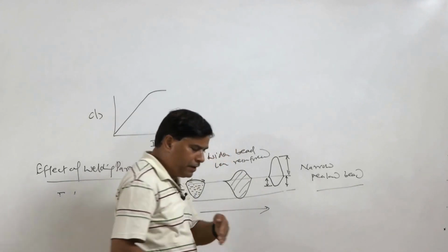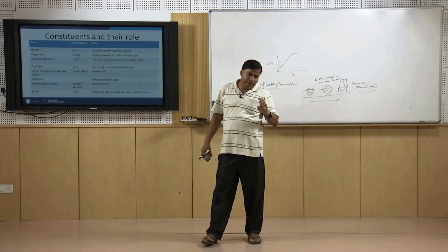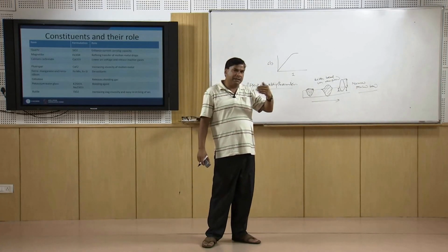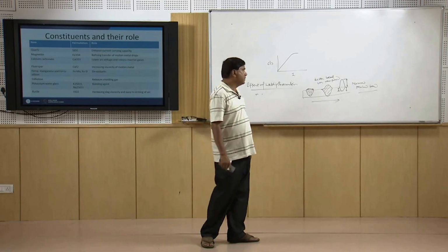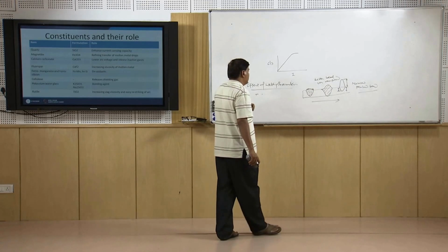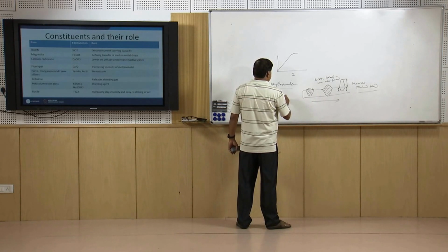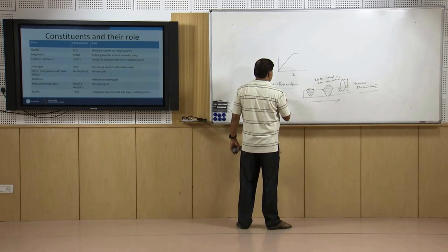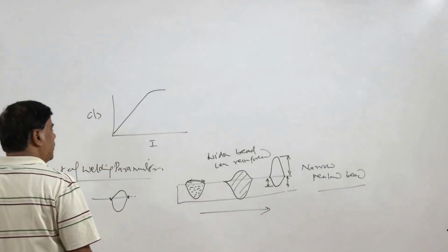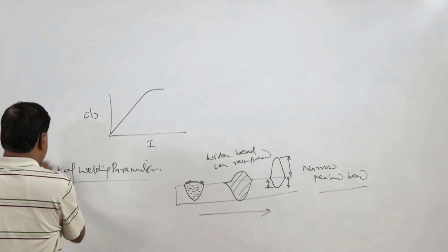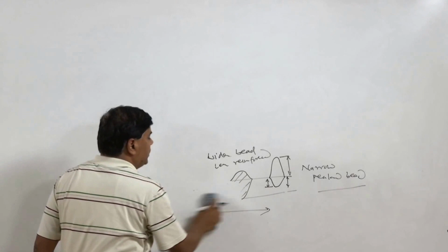And when we are moving very fast, then due to the high relative velocity with the ambient gases, it can deflect the arc, meaning arc blow can also take place. Sometimes undercut is also formed because little melting takes place on both sides. Near the toe of the weld, undercut is formed, which provides easy sites for stress concentration and can deteriorate the performance of the weld joint.